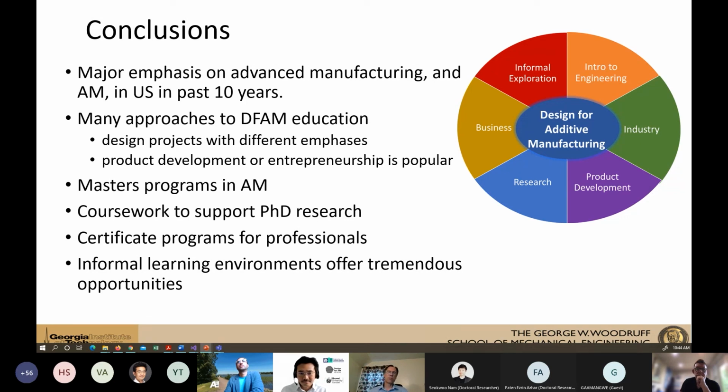If you want to do other things, like 3D packaging, where you have packages or electronics that have to conform to shapes or fit in small areas with special shapes, these are applications where I think additive can have a big impact, because it's difficult to use standard printed circuit board fabrication and population technologies there. So, said a slightly different way, potentially complex niche applications will be the first real area that'll see a tremendous amount of advancement. It'll be a while before additive takes over from conventional microelectronics and printed circuit boards.